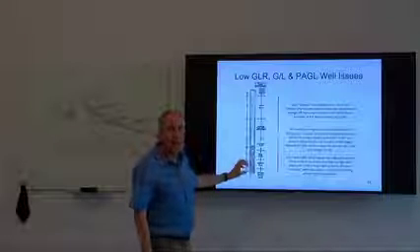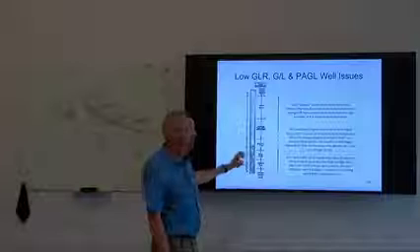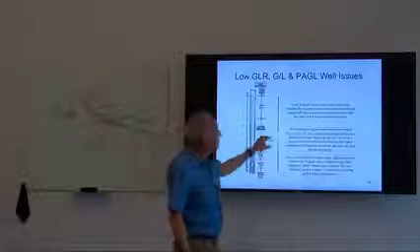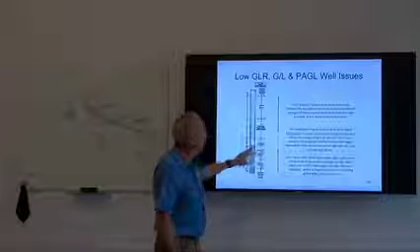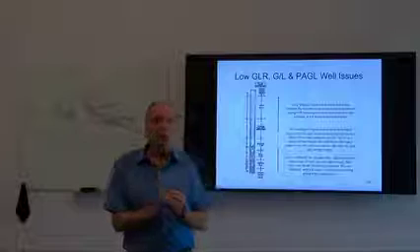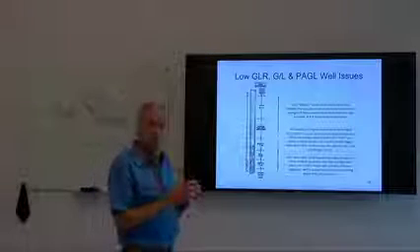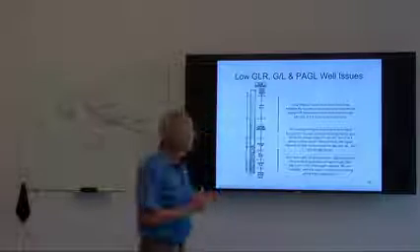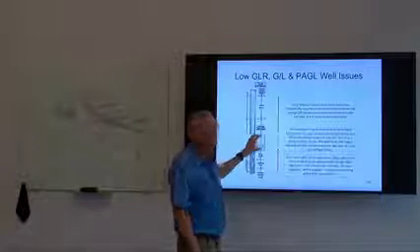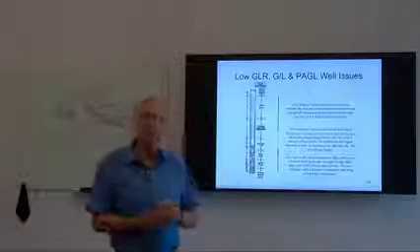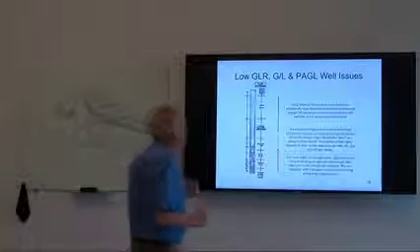Compressed gas occupies a very small volume. We have a relatively high liquid holdup. But as we move up the well, we can see that we get into a transitional area. And this transitional environment is where our gas is beginning to expand. It's taking up more of the volume. The gas is actually traveling a little bit faster now. And it is starting to be able to effectively move the plunger and actually pump liquids.